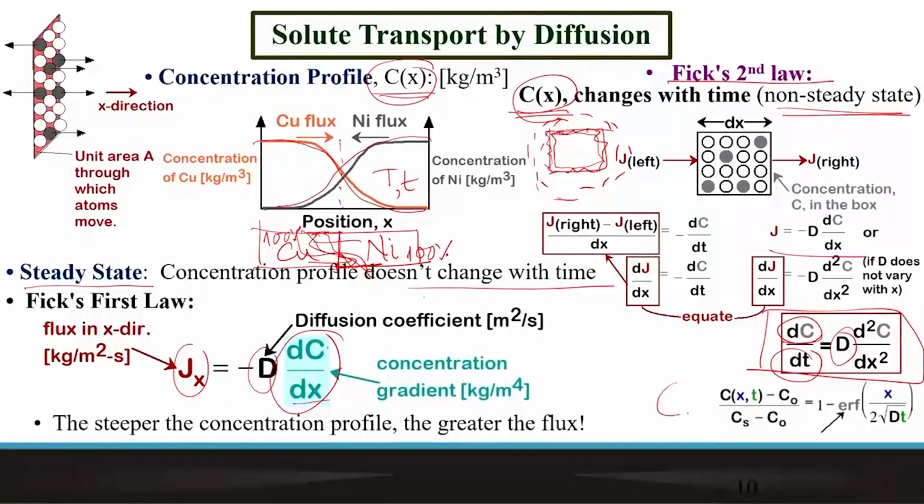So typically an approximate solution using the error function approach could be like this, where we see that the concentration difference is again proportional to the square root of time, and this is very similar to the earlier expression that we have seen before. So this x will be again proportional to root over t for the same isothermal condition.